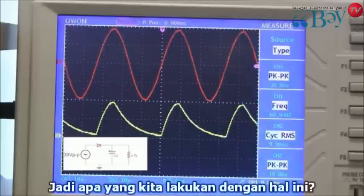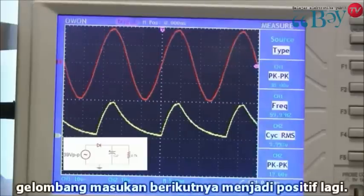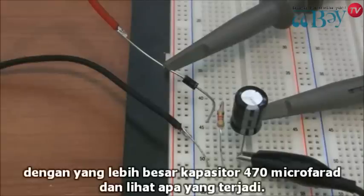So what do we do about this? Well, let's increase the size of our energy reservoir so that we've got enough to last us until the next time the input waveform goes positive again. Let's replace that puny 1 microfarad capacitor with a beefier 470 microfarad capacitor and see what happens.